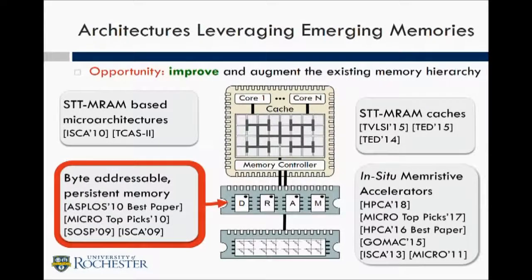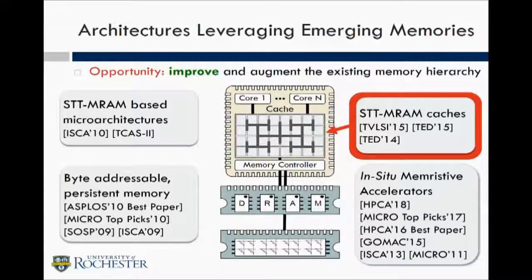You can take a step forward, and you can say, hey, actually, we can maybe replace the SRAM, which we today use to implement the last level caches, with STT-MRAM. And the minute you do that, you get some benefits as well, because the technology is denser, the footprint of the cache shrinks. Now the wires are shorter, the data movement energy is substantially reduced, and also because the technology is non-volatile, your standby power, your leakage power is significantly lower as well.